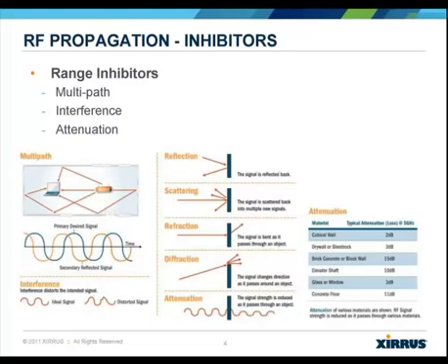Multipath occurs because when a transmitted signal leaves an antenna, it doesn't just take a single direct path to the receiving client. No matter how directional the antenna, there are always going to be multiple copies of the signal created. When the signal hits an object, whether it's a door, a wall, or pretty much anything, additional copies will be created. This creates a problem as the multiple copies of the same signal will have varying delays and arrive at the receiving station slightly varied in time.